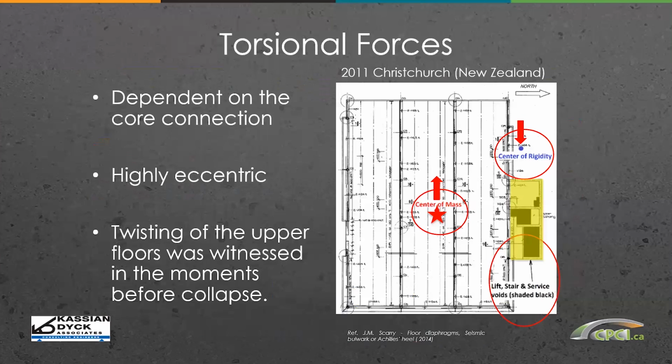How are you taking the diaphragm force from this large force plate and getting it to that far right wall? And then what are the resultant torsions going into the perpendicular walls? So that's a real complex load path there to try and take the earthquake force into the far right wall, knowing that you have openings due to the elevators and the stairs and just a small section of floor landing that can get to that far right wall. So that's a very complex design.